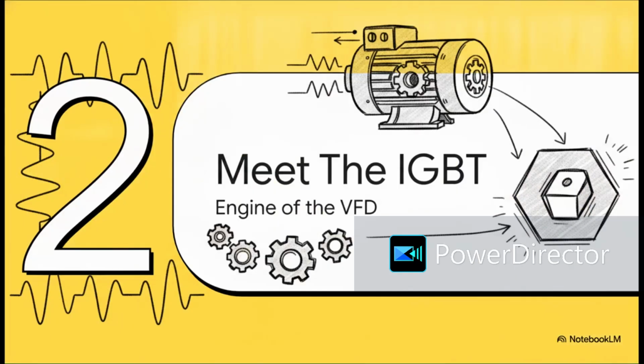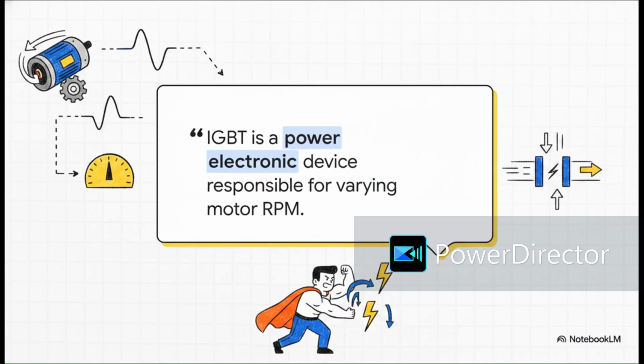Moving on to Section 2, meet the IGBT switch, the engine of the VFD. Right smack in the middle of that final inverter stage, we meet our prime suspect in this whole mystery. It's called the IGBT, or insulated gate bipolar transistor. Basically, it's a power electronic device that is primarily responsible for varying the motor's RPM to match exactly what you require. Think of it as this hyperactive, fast-switching gatekeeper that is rapidly turning power on and off to dictate the final output. It's doing all the heavy lifting.